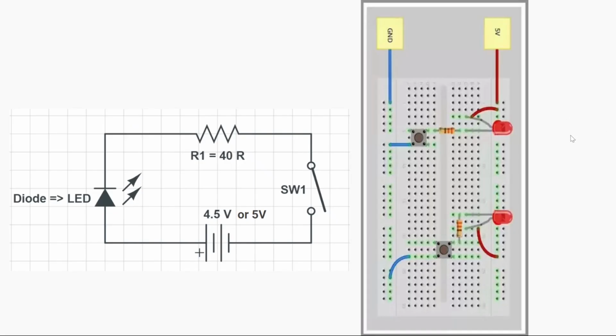Okay, so now we have the parts. We understood what we are doing. So let's try to make the circuit. The first thing I recommend is that you place your components, and then in the last carefully place or connect your power supply. Do not connect your power supply right at the beginning. It's a recommendation, and it will really help. So no connection on plus 5 volt or 4.5 volts, depending on what you're using, or ground. So leave them as is.